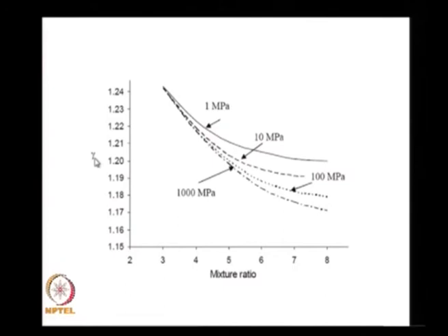Gamma, we said for the simple species like a monoatomic species it was 1.67. For more complex things like CCl4 and all that, it was lower at 1.12 or something. And what is it we find? We find that at higher pressure you have more complex products, and therefore the gamma is smaller. As pressure reduces, the value of gamma decreases, which is again in the right direction.